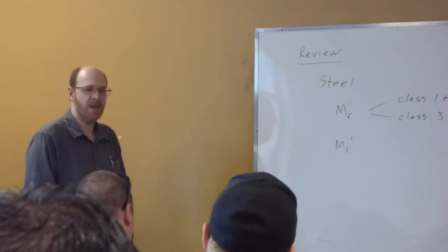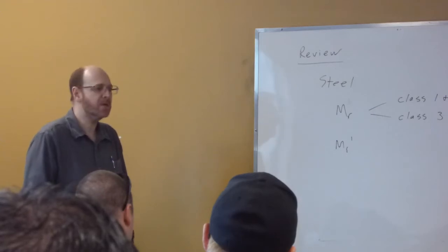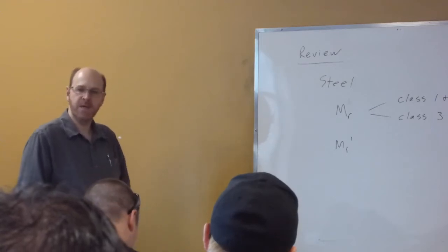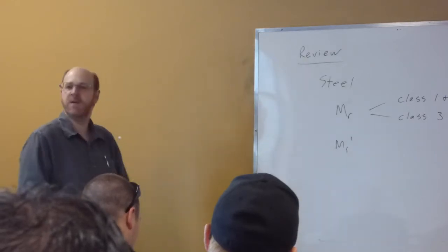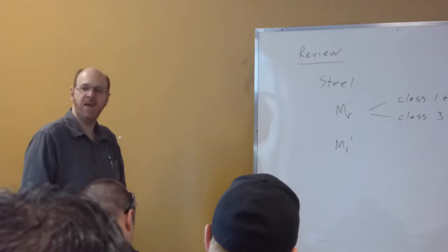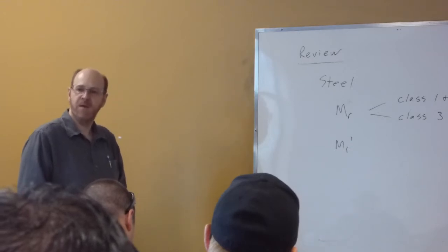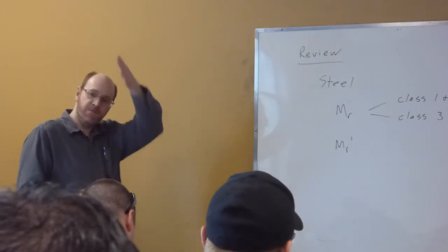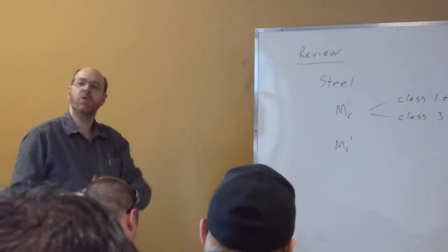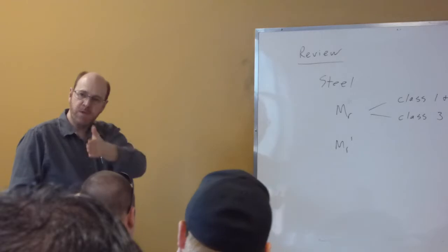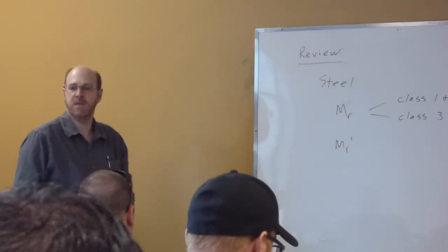It might be something that during the detailed connection design stage, the detailed connection designer might take a closer look at that and say, oh, well, I've got 5 bolts in here, that's a significant chunk of area, let's calculate the shear. If necessary, they might distribute it instead of 5 bolts all in a row, put it in as 6 bolts, but in 2 rows, right? So that the amount that you're reducing from one particular shear plane is minimized, right?